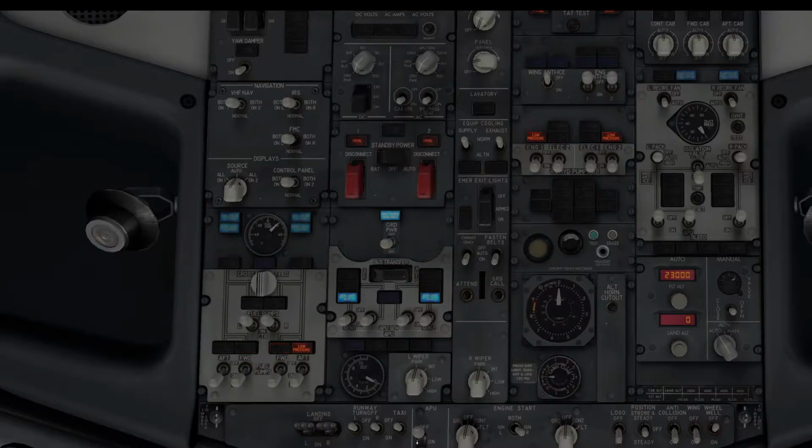First, fuel pump on, APU on. Okay, the cabin is secured. Have a good flight. Low oil pressure eliminates. Press the start for 3 seconds. 1, 2, 3, 4. Release. EGT is rising. It will peak at around 800 degrees and then slowly decrease.